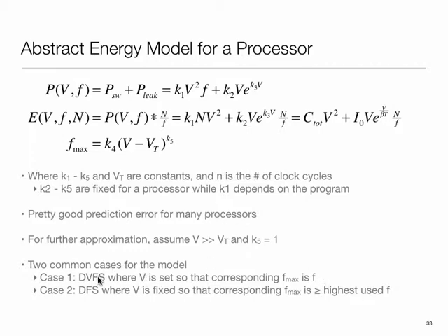So this ability to do dynamic voltage frequency scaling, where you essentially set the voltage and then the frequency is automatically set to the corresponding Fmax, or vice versa, where I set the frequency because I need a certain speed, and then the voltage is automatically set to the corresponding voltage. That's often found in hardware now.